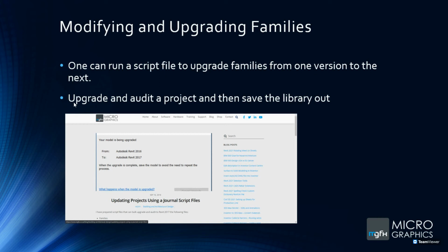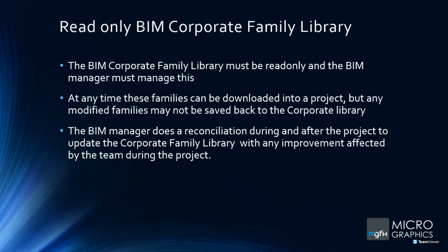well, let me give you an example. Somebody forgot to audit their model from one year to the next, carried on designing and designing and designing, and then eventually when they did the audit, they lost a third of their building. So you don't want to get into a situation like that. So you just want to make sure you do the required maintenance on the families, and you make sure that they can carry on into the future as you develop that library and maintain it.